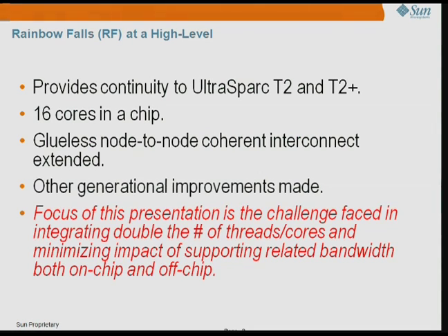It won't be an overview. Instead, I will focus specifically on the challenges that we as a design team faced in integrating 16 cores on a chip, and also in supporting the related bandwidth requirements of 128 threads on a chip.